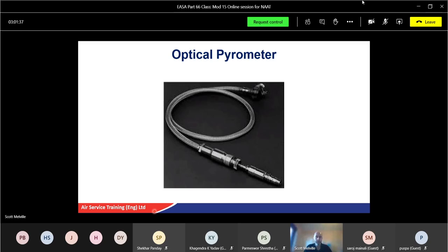For changes in conditions like a cold junction, the cold junction temperature is affected either by a bimetallic strip or by feeding intake temperature T1 into the system from another thermocouple. Now, the thermocouple in a T1 is normally made from what type of material? Yeah, iron and constantan. Good.